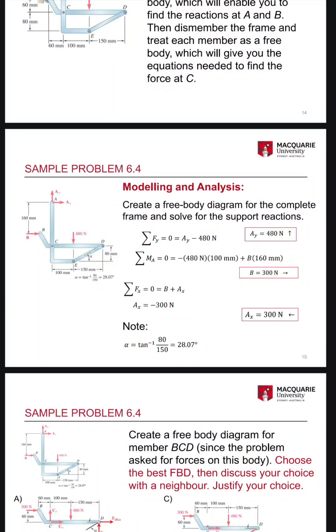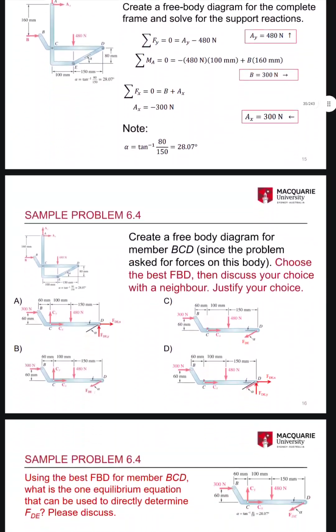Sum MA equals 0. So 0 equals minus 480 Newton into 100 mm plus B into 160 mm. B equals 300 Newton going right. And sum Fx equals 0 equals B plus Ax. Ax equals minus 300 Newton. So Ax equals 300 Newton going left. Note alpha equals tan inverse of 80 by 150 equals 28.07 degrees.